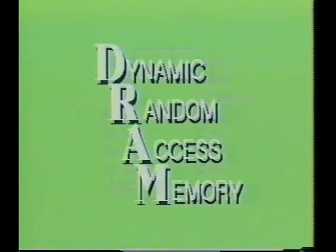Up until about a decade ago, electronic design engineers would avoid dynamic memory like the plague. Their reasoning was simple. The disadvantages far outweighed the advantages. The primary disadvantage was that dynamic RAM required a lot of support circuitry. It also required 3 supply voltages, and timing was most critical. But today things have changed. Today's inexpensive dynamic RAM devices are much easier to use and are capable of providing more memory for the dollar. Any circuit designer worth their salt must become familiar with this device.